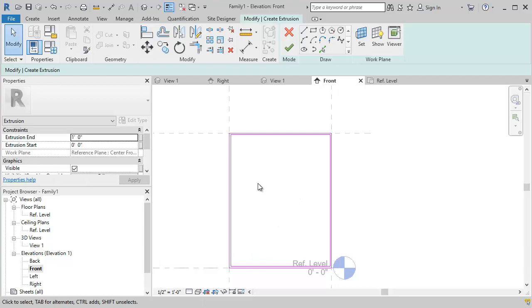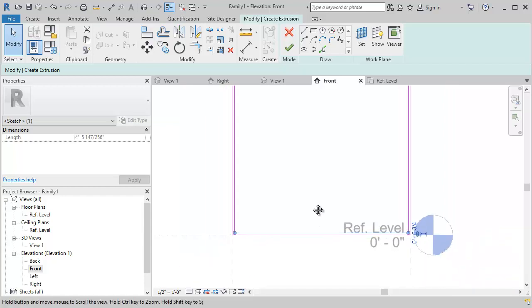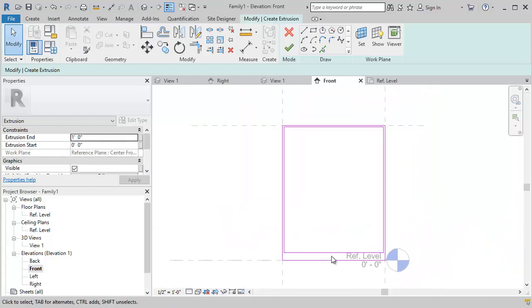Now, I'm going to leave that the way it is for now, and if it turns out I have to lock down the thickness of those between those lines after we start changing the size of the shelf, then we will. But for now, I want to keep it the way it is so that you can see what happens if we don't constrain that inside rectangle. So I'm going to grab the bottom line and move that up to a height of 4 inches. Usually a shelf base is a little bit higher. It's built in, and then all of our actual shelves that will array will come in here and go up. So that looks like that's going to work for the basic shelf frame.